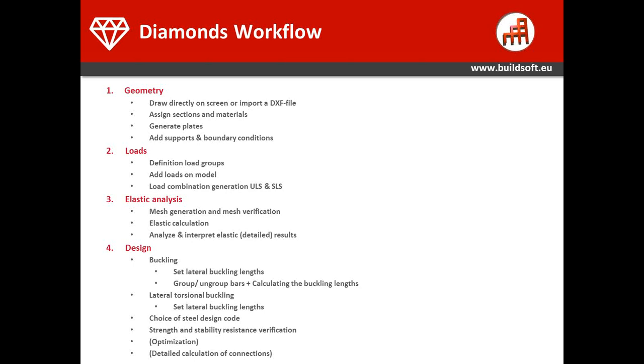We have a general workflow. There are 4 main steps: the geometry, the loads, the analysis, and finally the design. We always start, of course, with geometry. Here we will create the model by drawing in the software or importing it. We will assign cross-sections, materials, boundary conditions, supports.